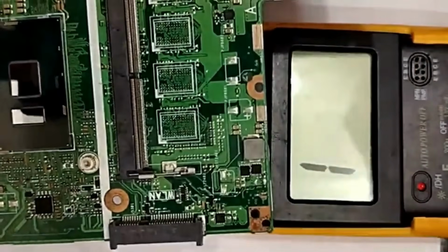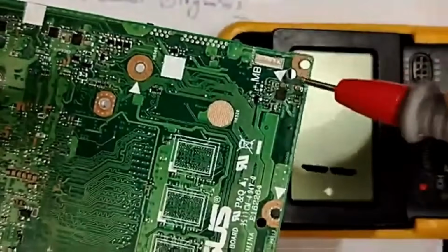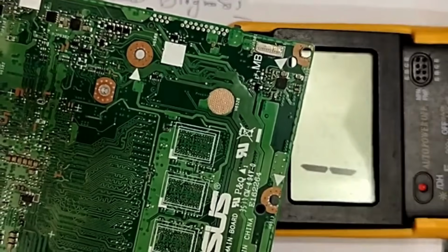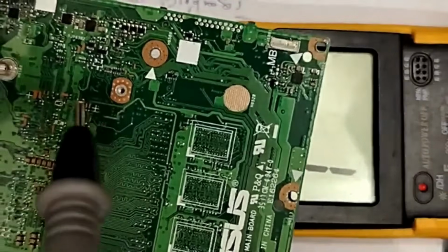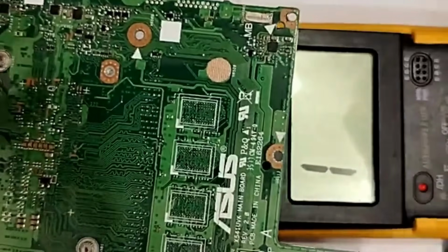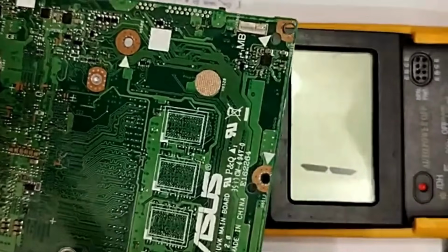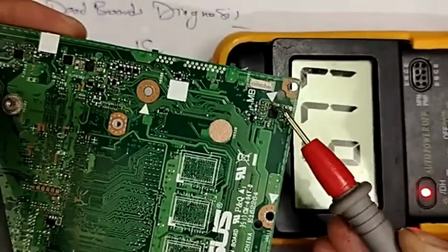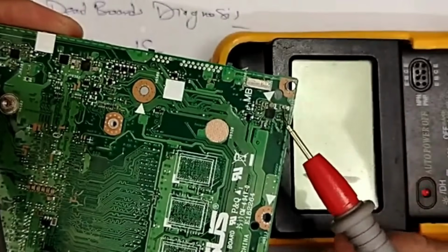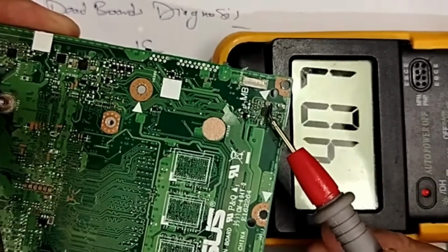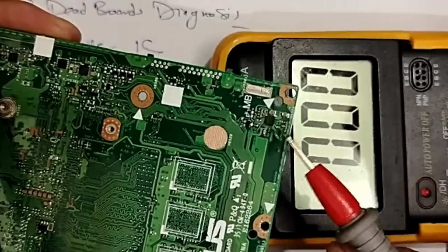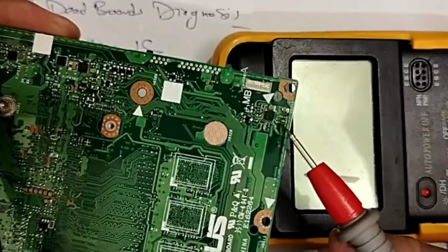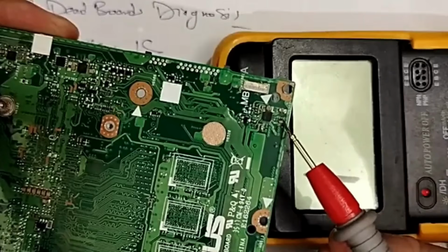Let's see the back here. Here we have the IC. You can just use the voltage injector. You can inject the voltage, that's it, and find the short. But then you cannot understand the technique. Here I show you the technique, my friend. So this is the IC. If we check this IC, 0, we have a short in all the capacitors here. This one, 0 on this side. Okay, let's check this capacitor also. 0. Okay.